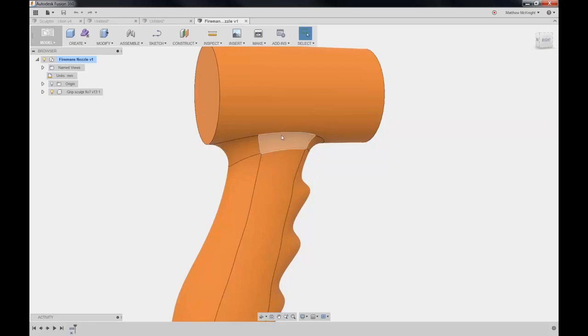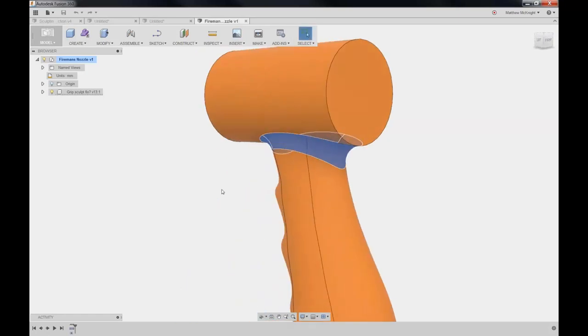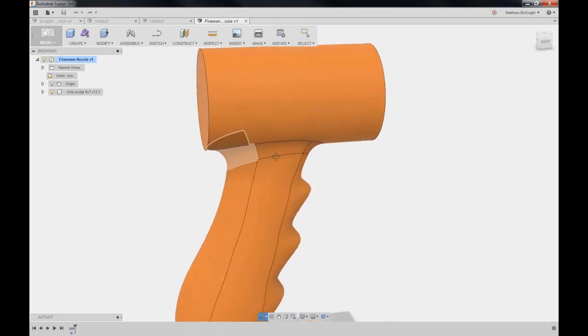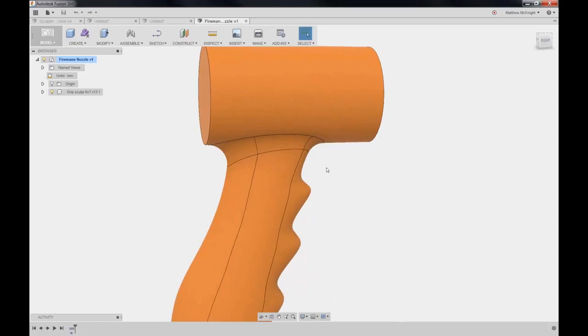The first one is traditionally you would maybe select, and I'm just holding down the control key, which enables me to then group select a number of faces. So the way to avoid having to rotate around and select faces in the background, in some cases it might be called the select other tool, is to click and hold down your left mouse button, and that brings up a dialog box where you can choose any faces or features that are either visible in the foreground or in the background, so hidden from you.